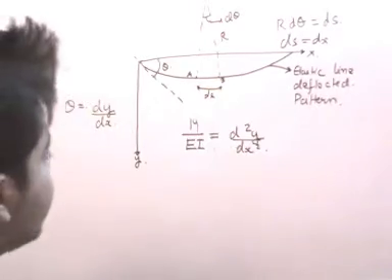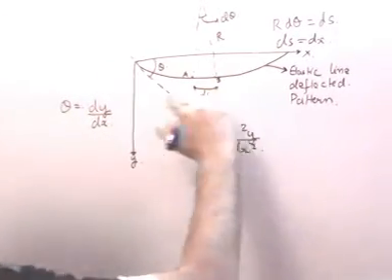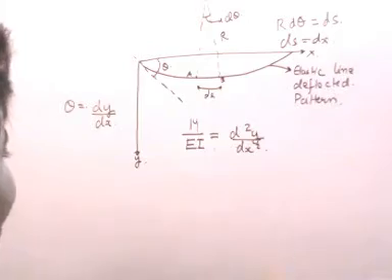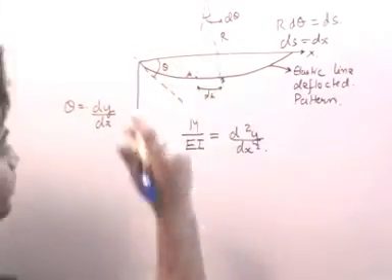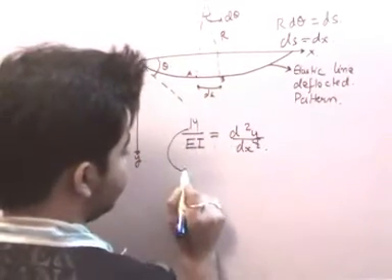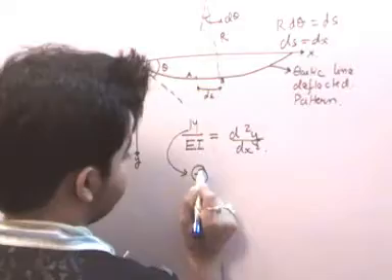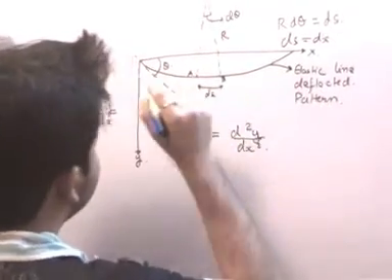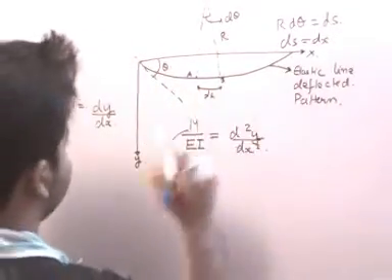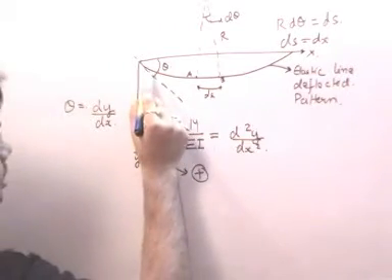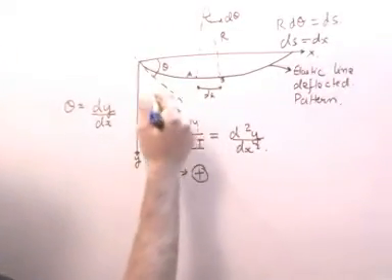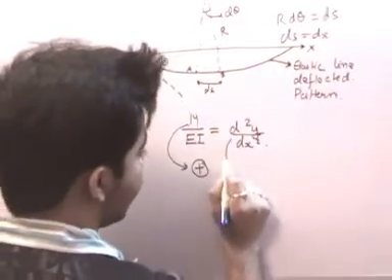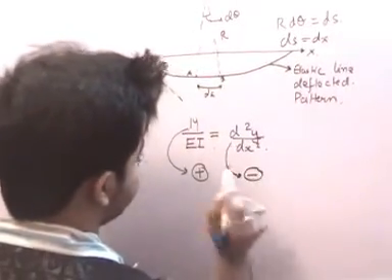Now let us see the sign conventions. This is an elastic deflected pattern, and here the bending moments are sagging moments, right? So in this case M is positive. Now d theta by dx is an algebraically decreasing function of x, because this change of slope per unit length goes on decreasing with x.